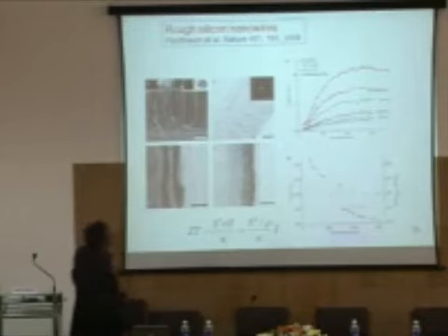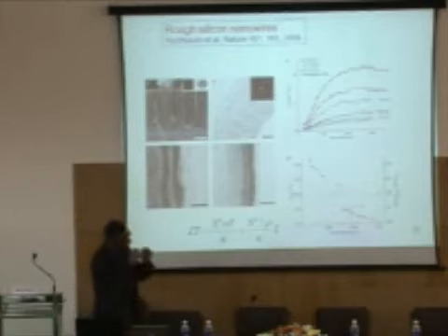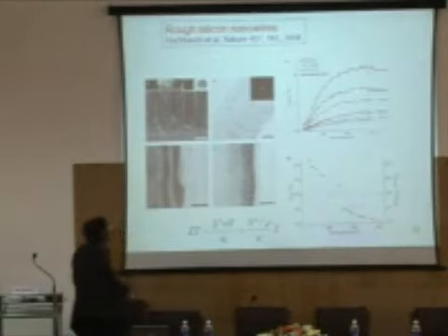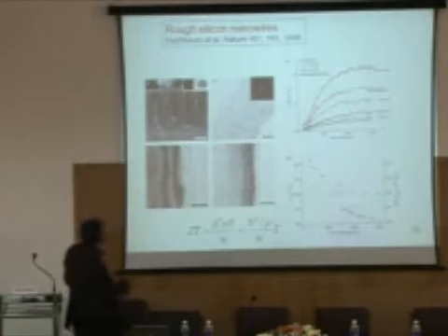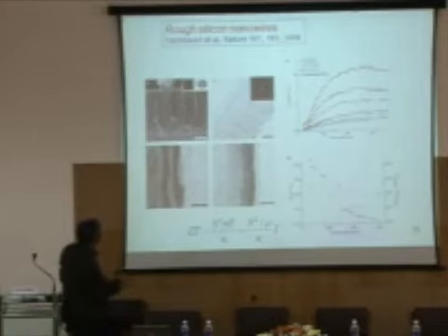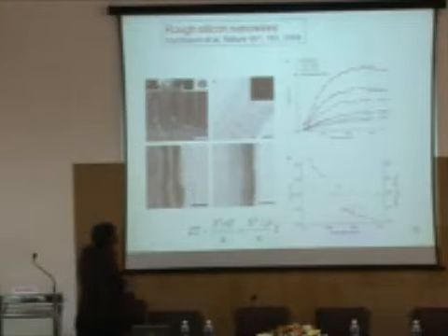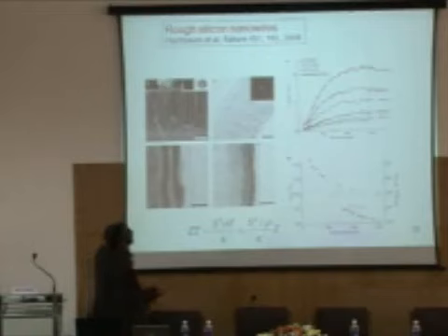Unlike the Caltech group, where they grew beautiful nanowires with very well-characterized surfaces, these people had two experiments. This is silicon nanowires with a nice, well-characterized surface. And here there's another one which was rough, with some modulations at certain lengths, a rough interface or surface. One thing they found, which was common with the other experiment, was again a dramatic reduction in the thermal conductivity as you went from a 115 nanometer diameter nanowire to 50.